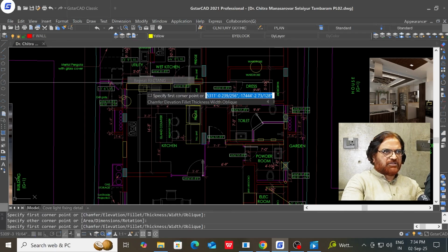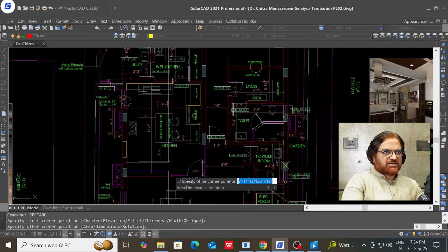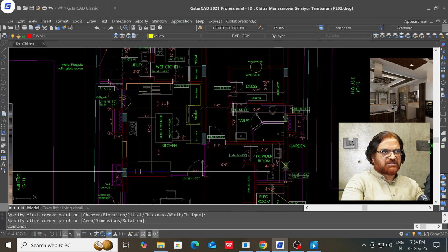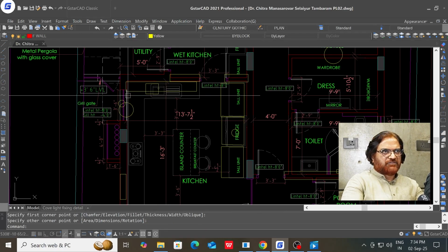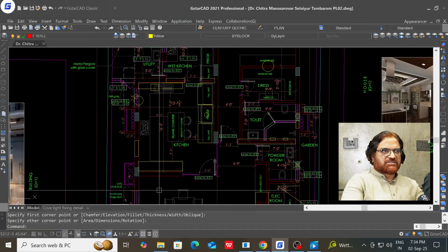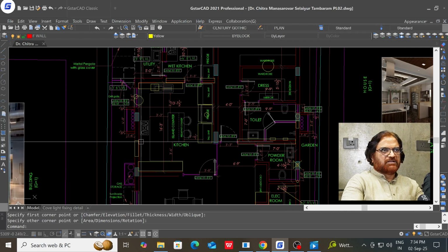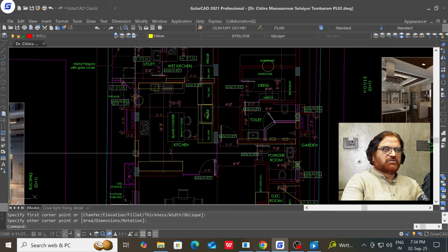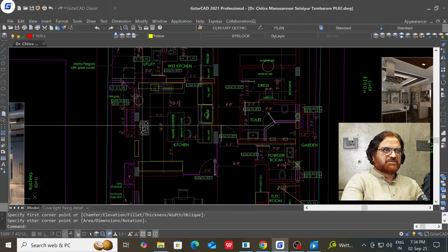Whenever you plan, you keep all the corners free of windows or doors. If you have a window in this corner, then you will not be able to place a proper wall cabinet. So let's have a proper wall cabinet. Then you can have a small window here. Then you can have the chimney here.